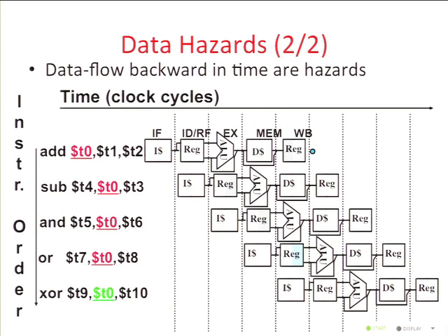This one actually works okay, because by the time you have to read the register for the XOR at the bottom, the register has been updated by the add. The value from the add is safely in T0 by the time XOR needs it, because there are 3 steps in between. So we're not always in trouble, just sometimes.